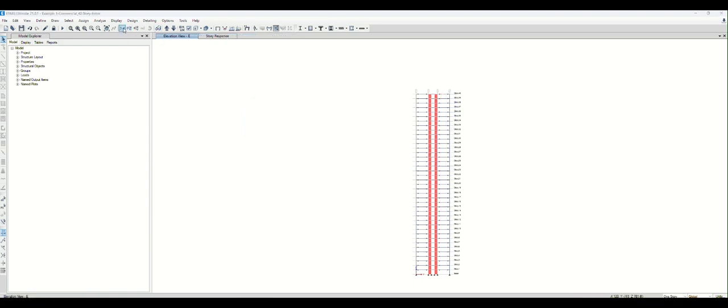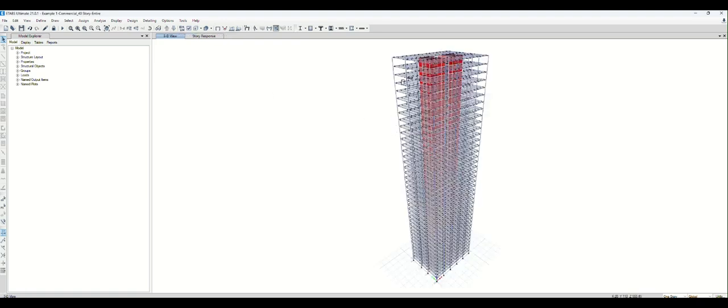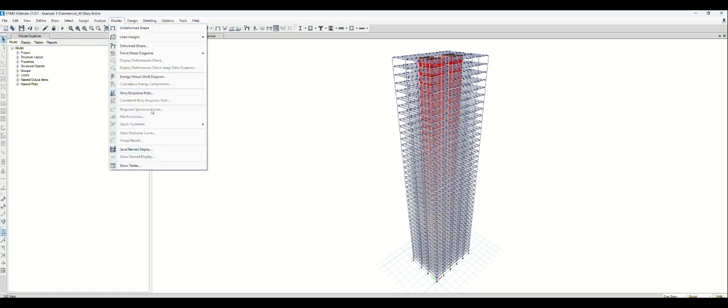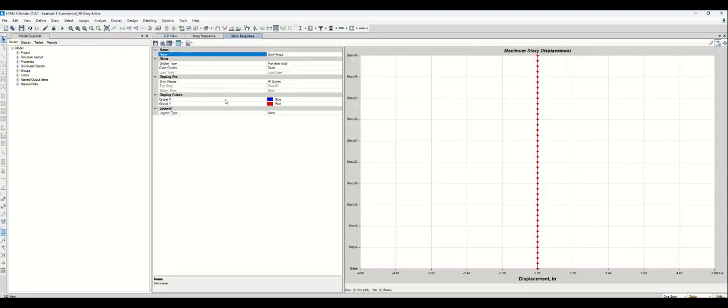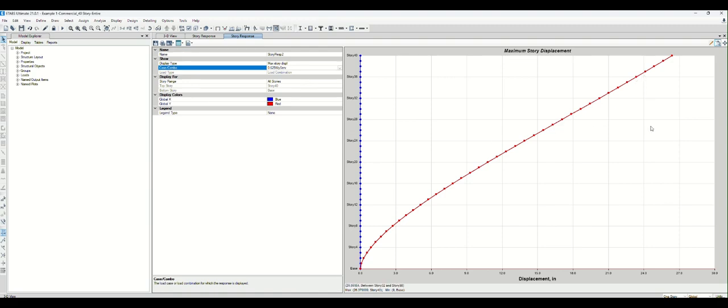So all right, we have the initial study based upon just pure concrete wall. I think its default is 12 inches. Now let's see how to organize your data, right? Currently you need to pay attention that the wind Y deflection is extremely too high.